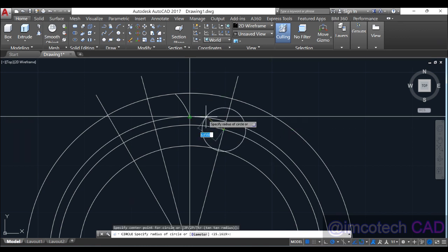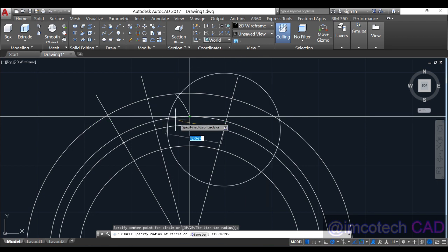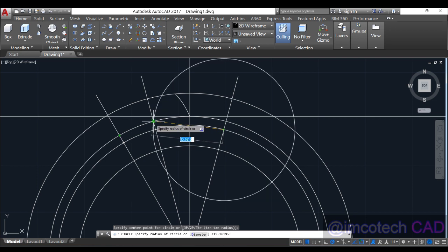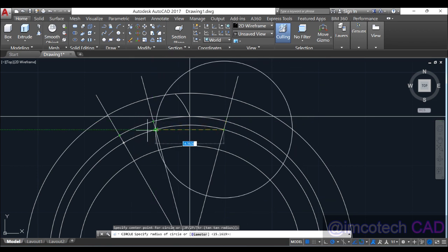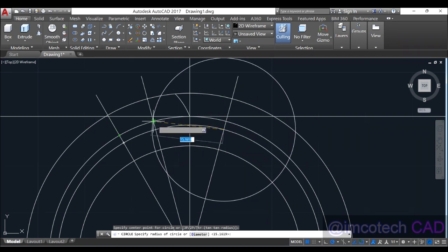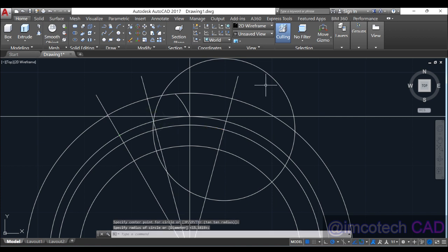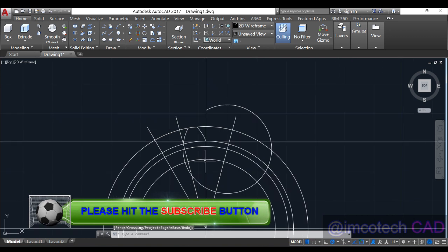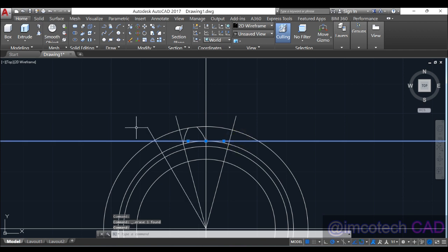So look at this. You will draw this now, not to this pitch point, but to this pitch point. Okay, look, pitch, pitch, pitch. So pitch point, because this is the pitch circle, not to the base circle place. This base circle is just the center, but the arcs will start from the pitch point right there. Now trim this and this. Okay, we're done with one of the teeth. Every other thing will be smooth for us. We can delete this line, it's actually unnecessary now.